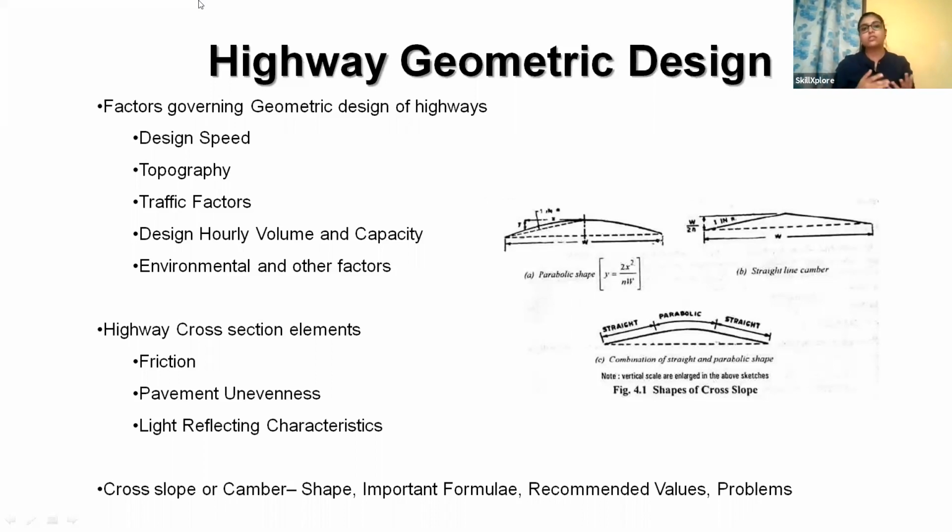So after that, the Tresaguet construction, Metcalfe construction, then Telford construction, and the latest and most recent one, the macadam construction, all those people considered the camber for their construction. For the camber itself, in the first, Tresaguet construction, they considered the slope for only the surface layer. They didn't give the slope for the subsurface or the subgrade layer. In that case, they identified the problem that if we are not giving the slope for the subgrade layer, then that causes some problem. So step by step, they identified the concept of camber right from the initial time itself. So we can understand how important the camber is.